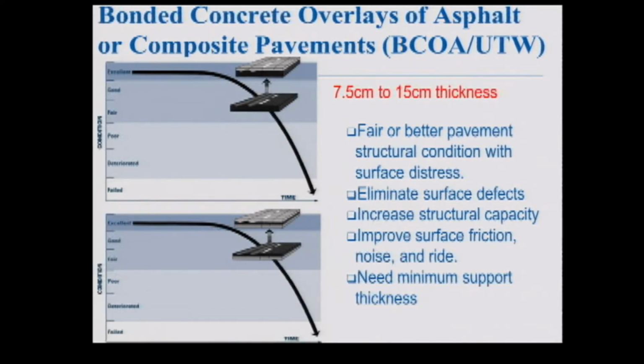But in general, as we design these, we're trying to restore some of the structural capacity, some of the ride, and in many cases, these bonded overlays are for reasons like rutting of asphalt that has occurred at intersections or bus stops. So that's where the main application began for these. If there's some fatigue cracking, you can do a bonded overlay. If you have a large amount of fatigue cracking, a bonded overlay really doesn't make sense because there's no structural